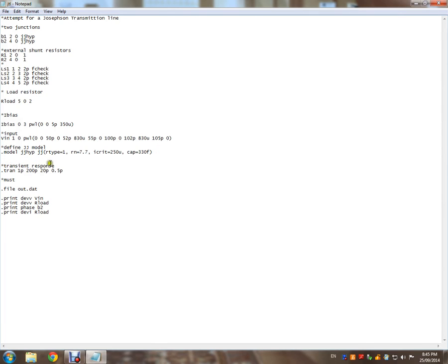Then you have to calculate the transient response. So .tran, do not type .trans, because you're going to waste 1 hour trying to find what's wrong. 4 arguments. Where does it start? Where does it stop? What's the step and the time step in between? You don't need all of those. I guess you could do it with 3 arguments, but if you want a very high resolution, you play with those. And if it's, for example, 1 minute, then you have to set that to, I don't know, do the calculations like 60 seconds. 60 seconds will give you an enormous amount of data.